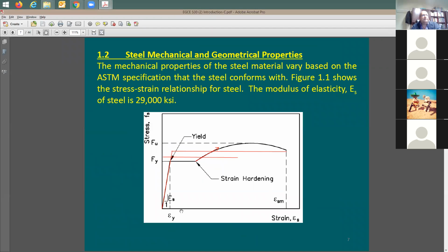This is exactly what I need here. If you like to consider your stress-strain relationship to be elastic, perfectly plastic, the performance is going to look like this. This is elastic, perfectly plastic. You see this, what happens? I'm just ignoring the strain hardening, right? You follow me, Maheen? Yes, sir. So if you consider that you have elastoplastic performance, the moment frame is going to be failing in this case.